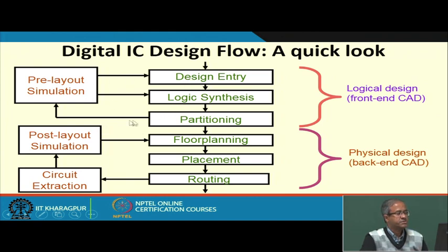So, you can carry out simulation before your layout is created, or after your layout is done, then also you can extract the circuit and you can do something called post layout simulation, which will of course be much more accurate. So, roughly this is how things work.